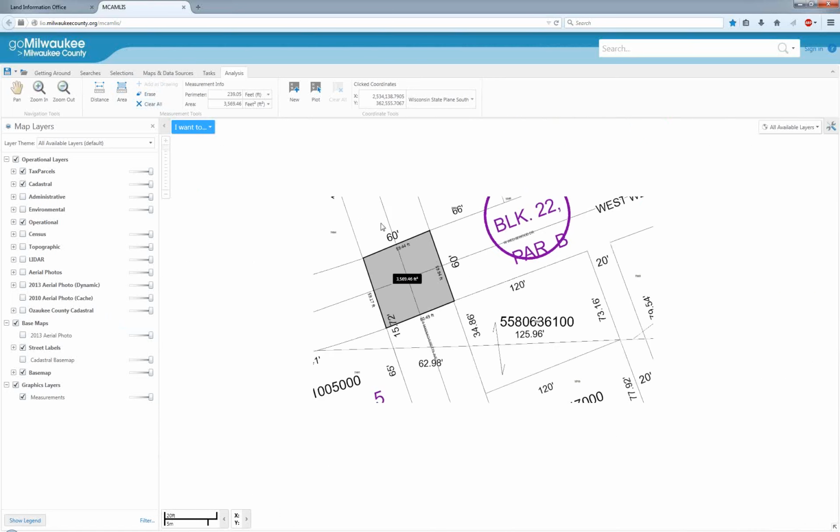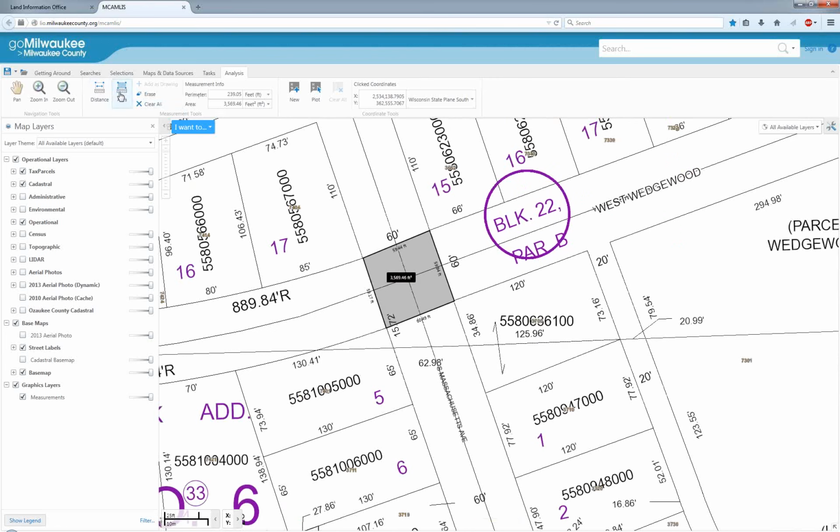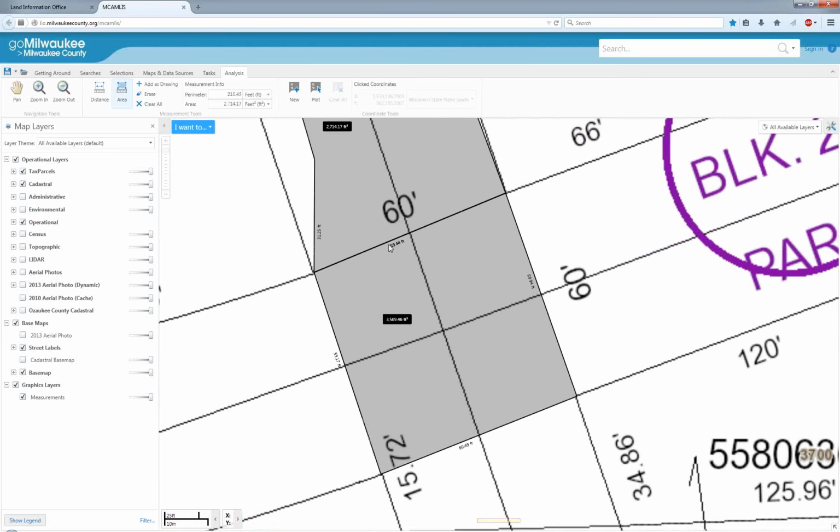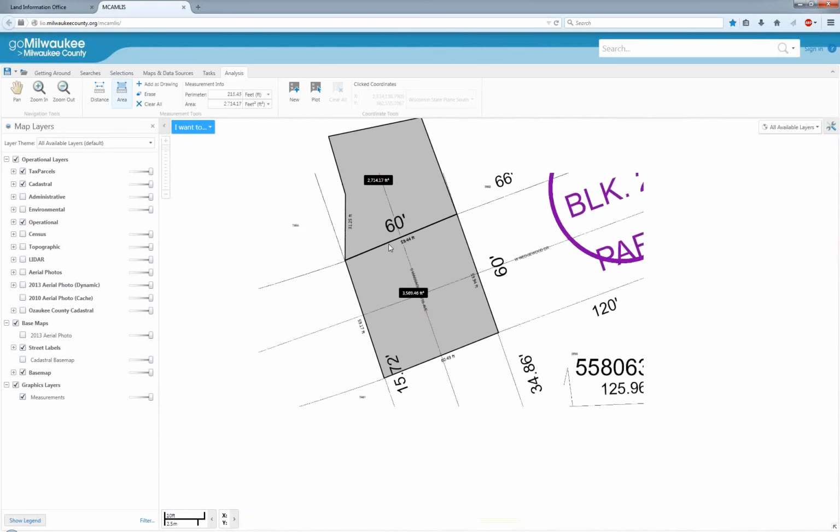There is one more thing you can do. Let me draw an area here again. It's hard to see on here, but I'm holding the control key, and this will automatically connect or snap to corners. So let's say I want to snap to this corner. Okay, I'll snap there, can snap to this corner, and that way there's a nice clean line in between these. So that's the control key.